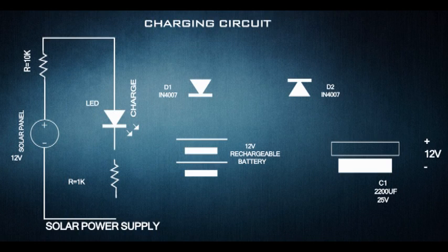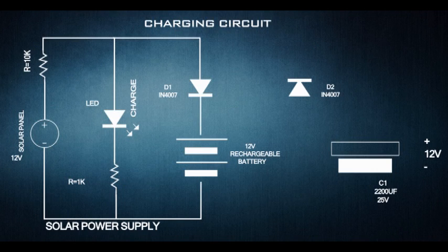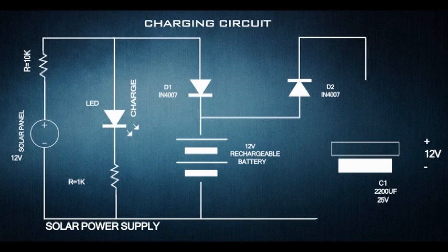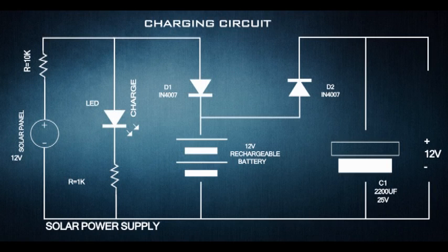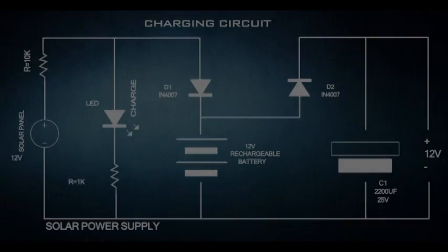The circuit uses a solar-powered battery power supply. During daytime, the battery charges through resistor R1 and diode D1. This charging mode of the battery is indicated by a glowing green LED. During night time, current from the solar cell decreases and D1 is reverse biased. At the same time, D2 is forward biased, providing power to the circuit. Resistor R1 restricts the charging current and the high value of capacitor C1 acts as a buffer for current. The diode used is 1N4007 and the capacitor is 2500 microfarad.